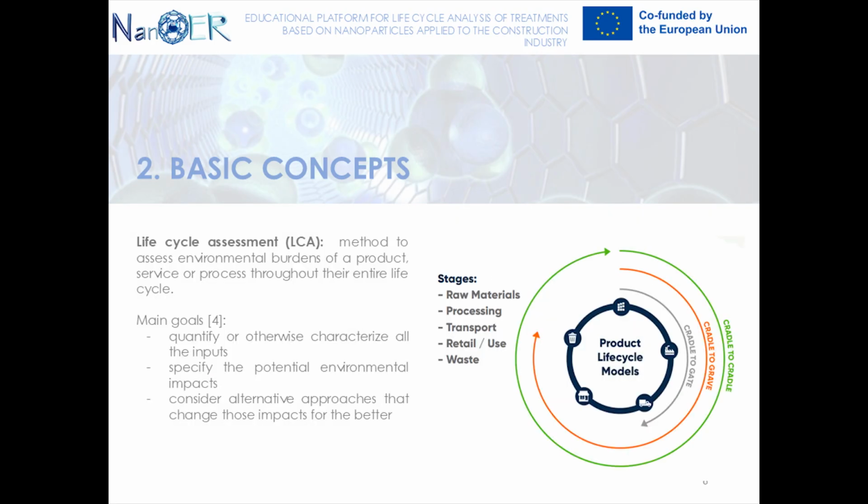Life cycle assessment, LCA, is a widely used method to assess environmental burdens of a product, service or process throughout their entire life cycle, from the extraction of raw materials to their disposal, from cradle to grave, in order to assist consumers in making decisions that will benefit the environment. The main goals of LCA are to quantify or otherwise characterize all the inputs and outputs over a product's life cycle, specify the potential environmental impacts of these material flows, and consider alternative approaches that change those impacts for the better.